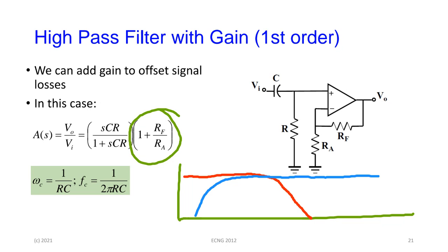If I cascade them, and notice they sort of overlap in sequence, if I cascade a low pass filter and a high pass filter, I'm going to get a response that looks like this, right? Which is my band pass. And in fact, that is one way of creating a band pass filter response, right? That's one way of doing it. And tomorrow we're going to discuss that in some detail, and we will look at higher order filters.